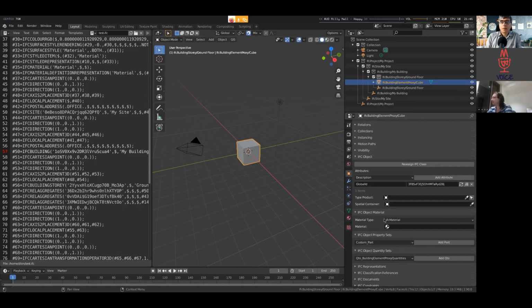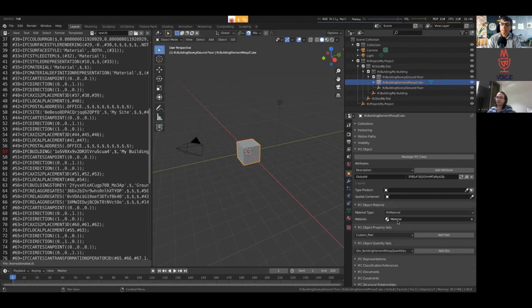And it's like materials, right? They can select a material, they can pick from a drop down, or if you want to create a new material layer set. This is actually one of the newer features in this release as well, which is much more friendly to users. You can see it has a much improved way of representing materials. And in IFC, there are 4 types of materials you can assign to an object. Should we talk about this now? Sure, go ahead.